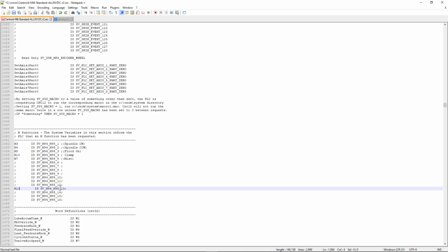It makes it simple. Now, once again, this M13 is just a label that's going to be used in the rest of the PLC logic. This can be labeled anything you want, but to make it easier for troubleshooting, we call it the same macro number that it's being used. So like that, when you're using things like PLC Detective, which I will go over later, when you see the M13 being highlighted, it means that the actual custom macro was being called and it set that bit. Okay?